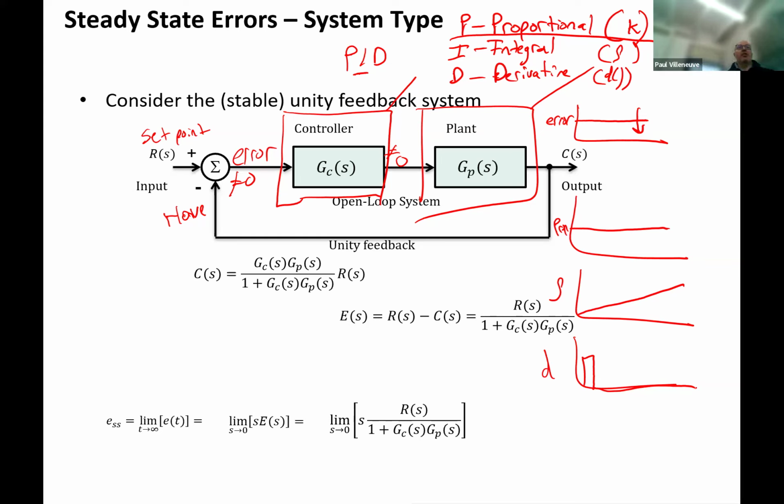Derivative is usually there to slow a system down. Think about a thermal process where you're trying to control the temperature of something. The difficulty of a thermal process is the temperature is too low, so you're putting more heat into a system. The temperature doesn't instantaneously change in that process, right? It takes time for whatever you're trying to heat up to heat up, but then also you have a device that's measuring temperature, and that has a time constant as well.